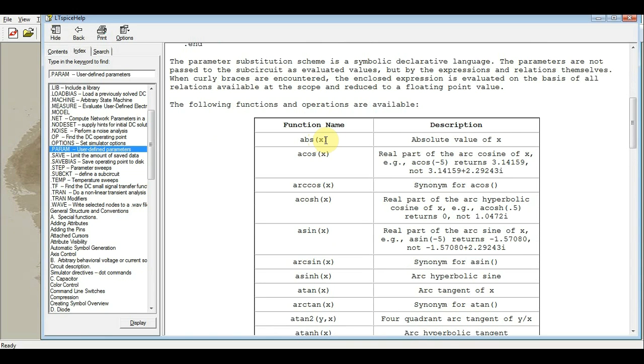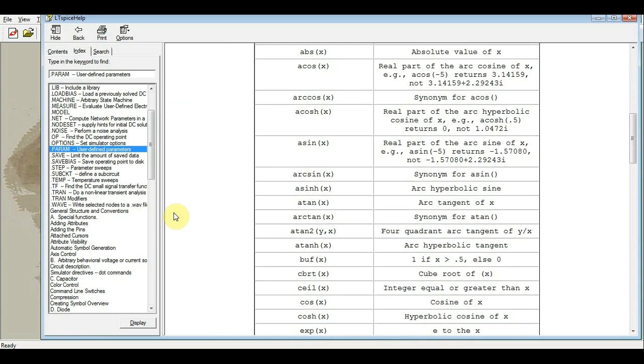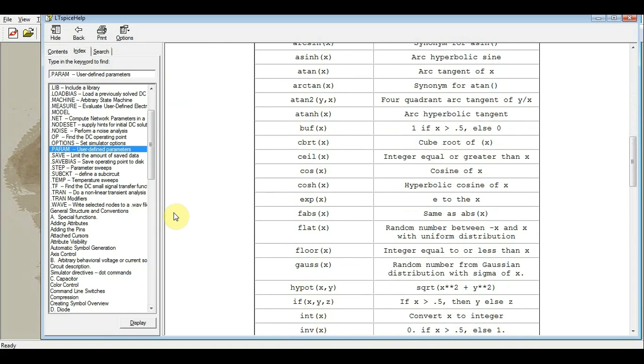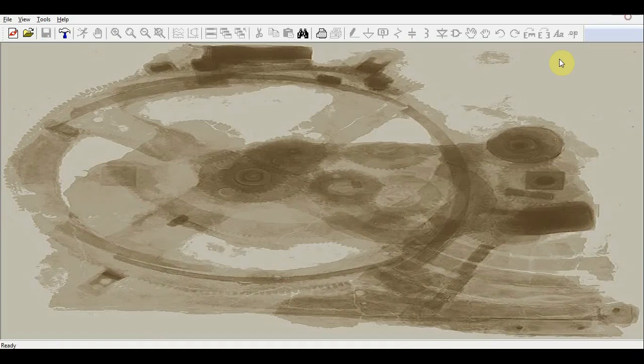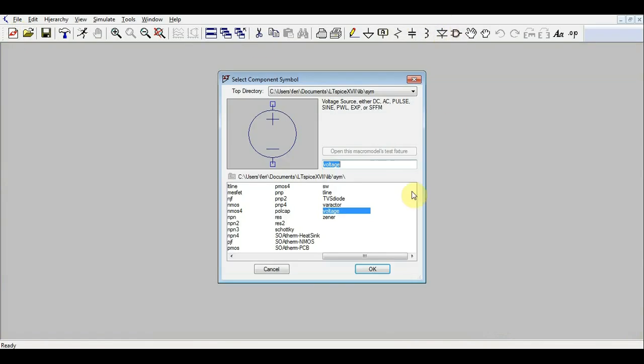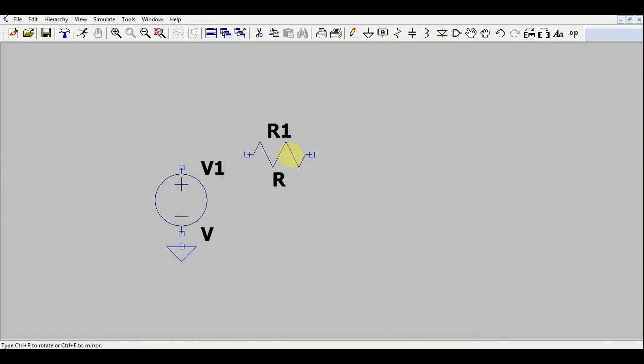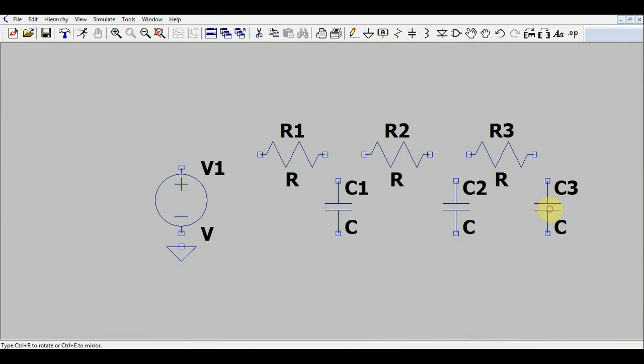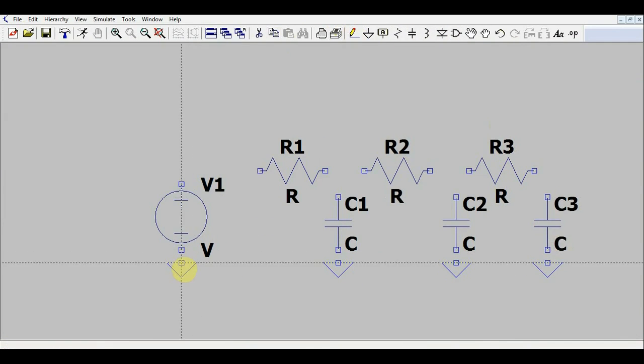An important thing to remember about the parameter is that it's a constant throughout the simulation, meaning it can only take one value for a single run of a simulation. So, what is this useful for? Well, one use is attributing the same value to multiple components. Let's say you're working on a multi-stage passive filter, and you want all components to have the same value.